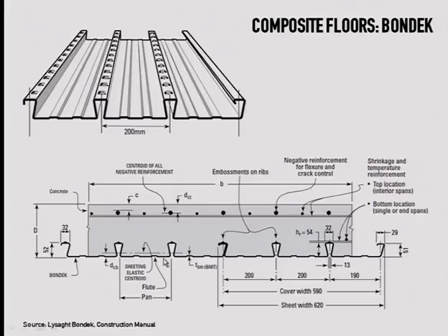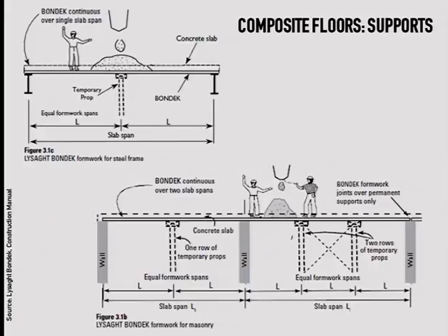In this bottom part, this profile here can be used to hang the hangers for the suspended ceilings. So that's used for that. And just a few schemes, you probably know that. Temporary props with diagonal bracing while pouring concrete, because of course the sheet is not able to resist the forces yet, until it's cured.